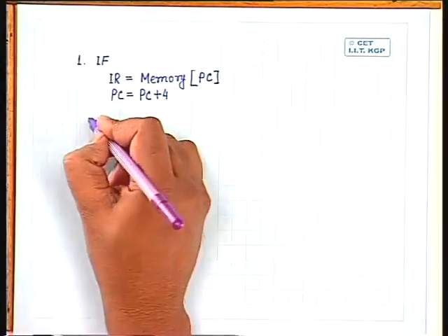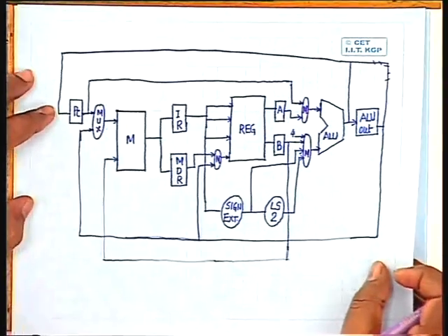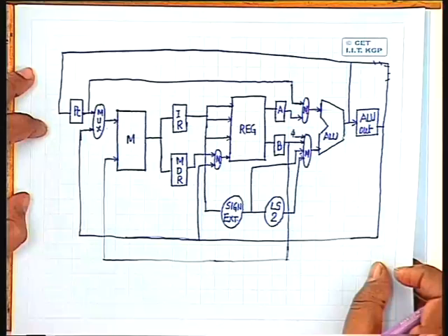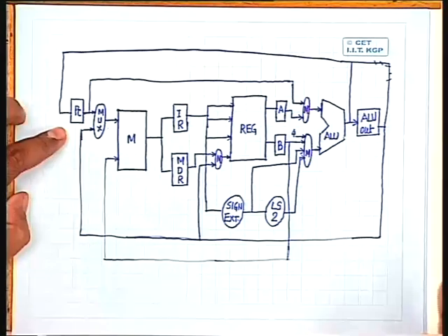During the second clock period, if you connect it like that, all the outputs of ALU will go directly to PC, but only that one will be loaded into PC for which the PC write enable is active. Okay.